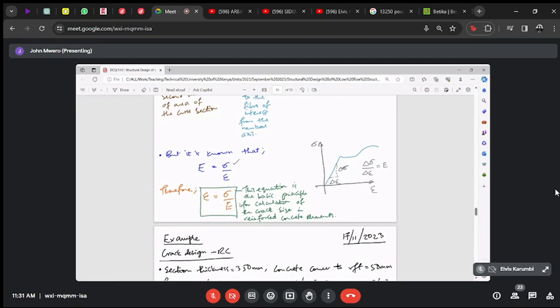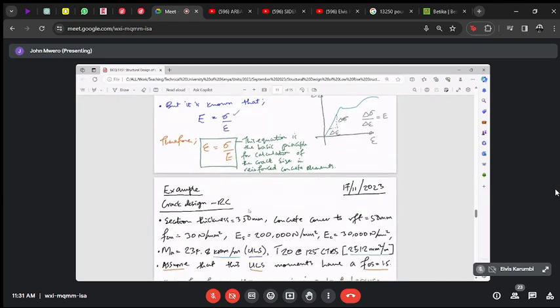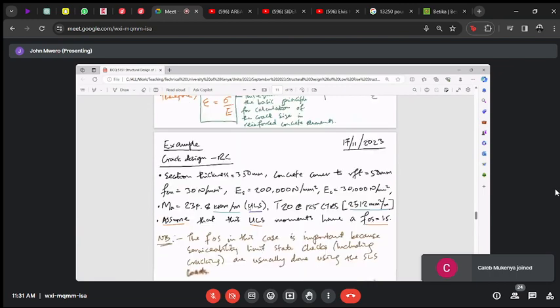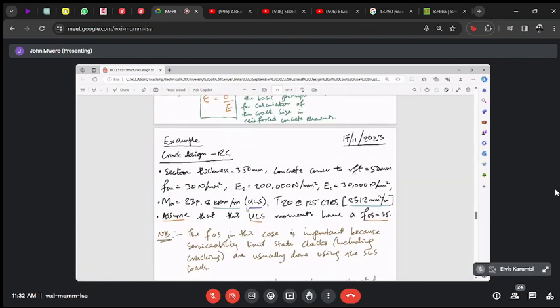Once we can calculate that, then we can go ahead and say, so what is the stress-strain relationship of this material that is concrete? And therefore, then we can proceed to calculate the crack sizes, because we know how much strain concrete can take before cracking. So anything beyond that, then it contributes into the crack. But we will see some detail today on these thoughts.